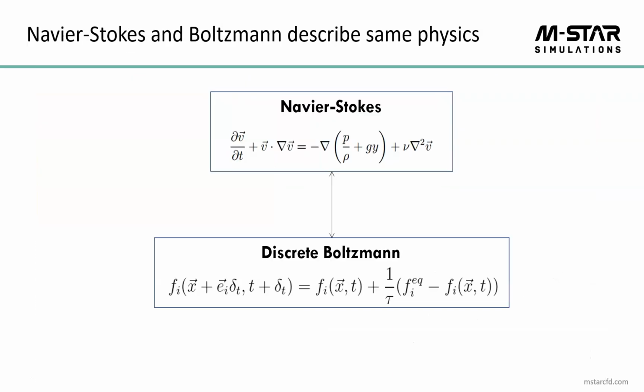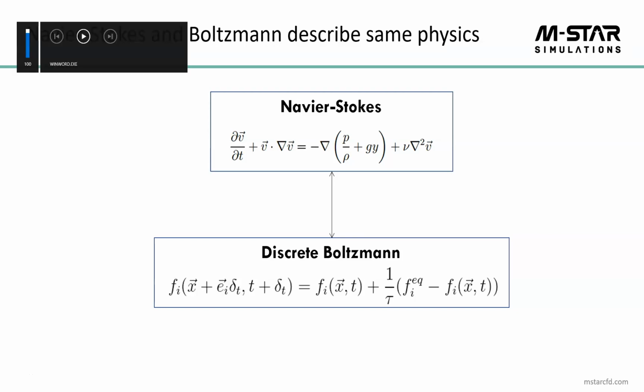So within the context of these equations, and I'll focus here on the Navier-Stokes, which was the conservation of momentum, and a lot of folks have probably seen this. Our most common approach for solving the Navier-Stokes is to, well, break it up into little bits and then use the computer to solve how the velocity field and the pressure field vary across the domain. This is what a lot of CFD tools do. A lot of users spend their time making a mesh upon which they're going to solve these equations. And from these codes, we typically get a steady state representation of the time averaged mean flow field.